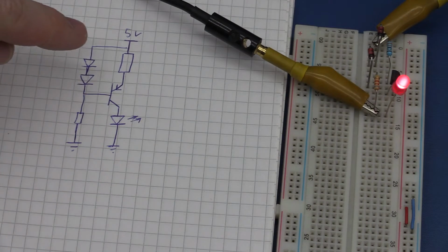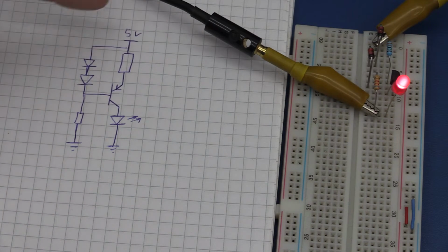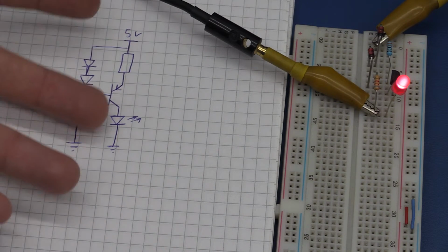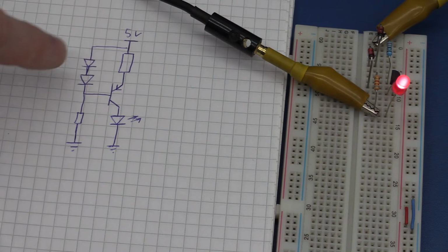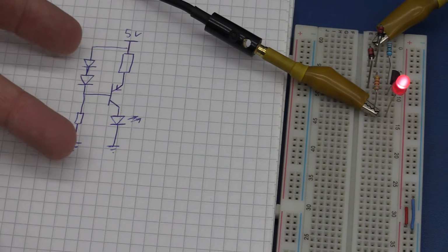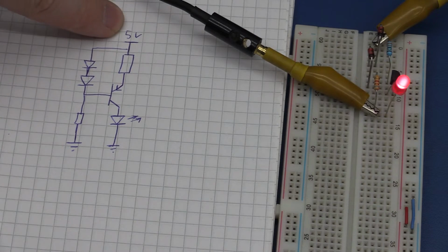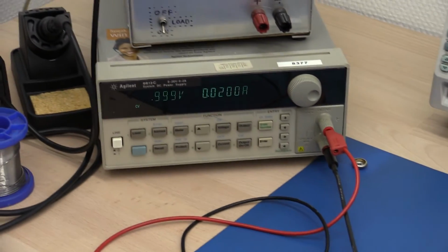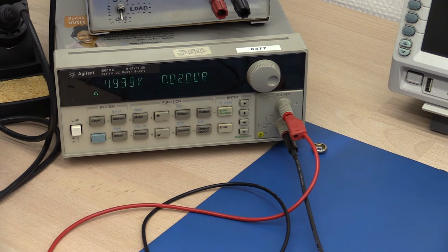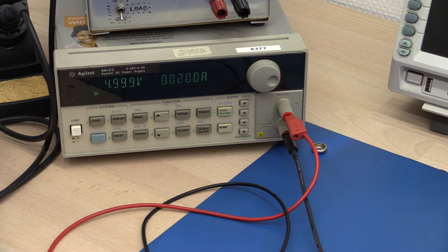And if you want a current source instead of a current sink, you can make that exactly the same, just using a PNP transistor instead and flipping everything. It's the same values and components except for the transistor, and then the location has been swapped to reference the high side. It gives exactly the same result, except I was very lucky to hit exactly 20 milliamps.